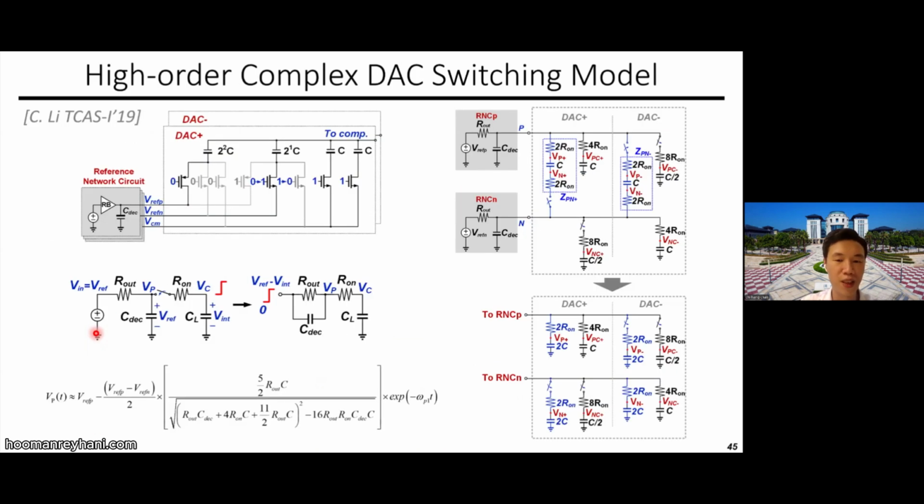Actually, we have done a very thorough analysis on this problem. Here we derive the equivalent model for this VCM-based ADC, and the requirement on the reference buffer: if the reference buffer does not have a small enough output impedance, how it will affect the ADC performance.